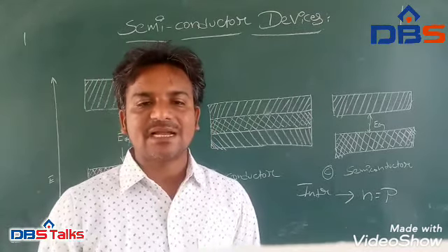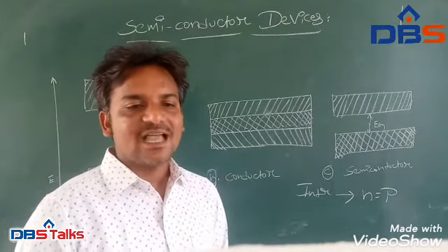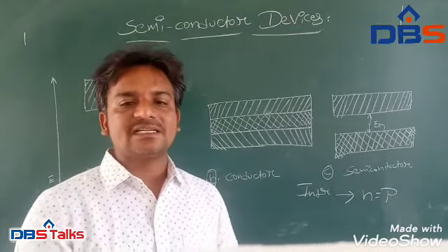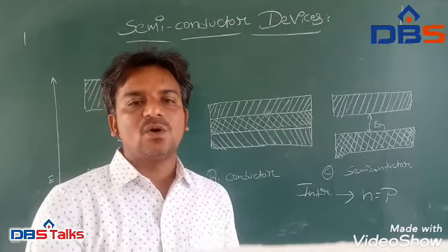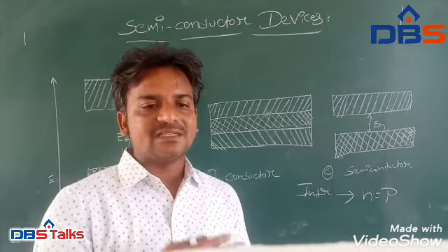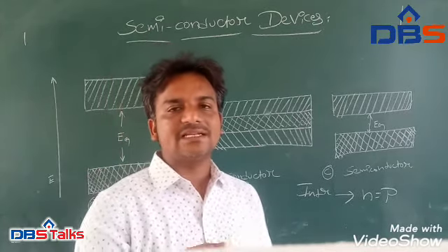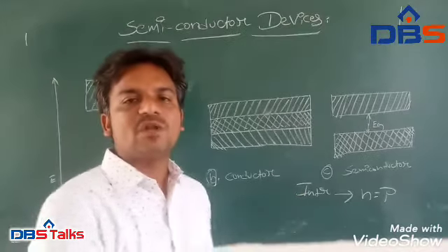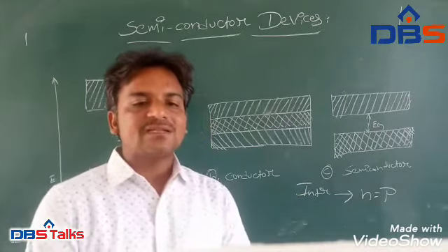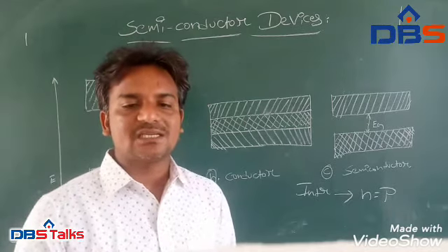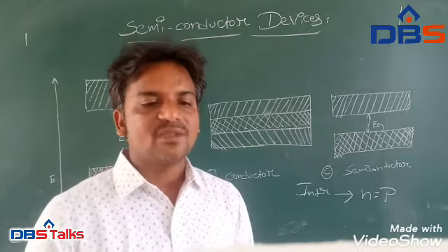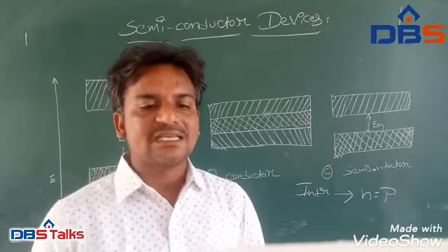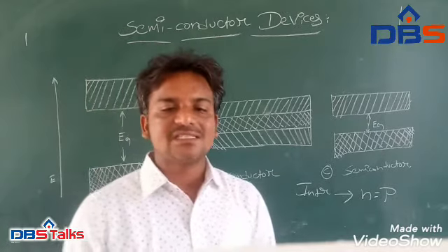In an N-type semiconductor, the dopant contributes extra electrons, dramatically increasing the conductivity. Based on the increase in hole and electron conductivity, we get pair generation, and the electron and the hole move from one side to another. In a P-type semiconductor, the dopant produces extra vacancies or holes, which likewise increase the conductivity. It is however the behavior of the p-n junction which is the key to a variety of solid state electronic devices.